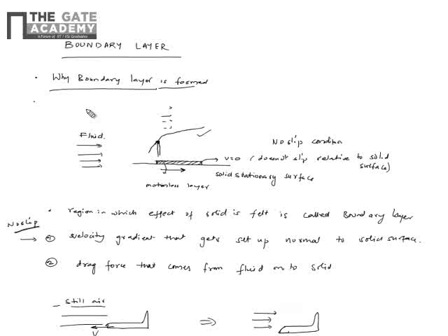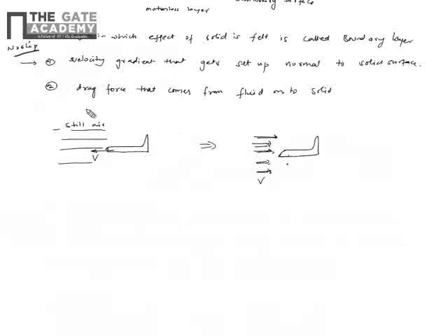When you simulate all this flight testing, you keep the flight stationary in a wind tunnel, and you move the air with the help of a compressor. You compress it and then move it with very high velocity in the wind tunnel, just to simulate what happens in reality, where the aeroplane moves in still air. So you're just modeling the same problem in a different way, giving the fluid velocity v and keeping the aeroplane stationary. On this, the fluid tries to drag, because the immediate layer in contact with the surface of the aeroplane becomes stationary, and then the presence is felt up to some layer.